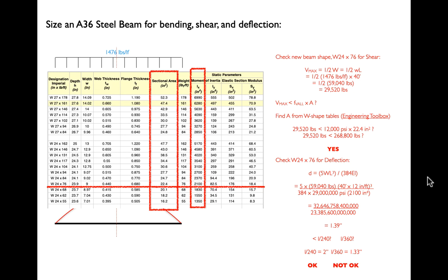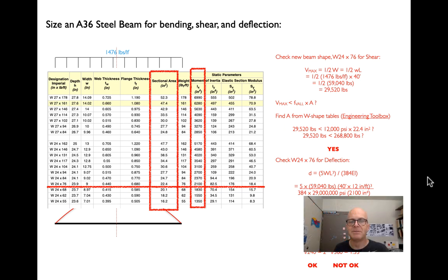Okay, we'll do 1 or 2 more of these videos where we look at examples of beam design. This is an important thing to understand just because it's something that will happen all the time in practice. Also because it deals with so many things, it's a good way to remind ourselves of all of the mechanics at work. We'll do a steel beam with double cantilevers, similar span but with cantilevered ends, and we'll look at what that does to the numbers. And then we'll also look at a rectangular timber beam, and we'll get some practice in kind of backing the section modulus out of the formulas that go into finding S for a rectangular shape.